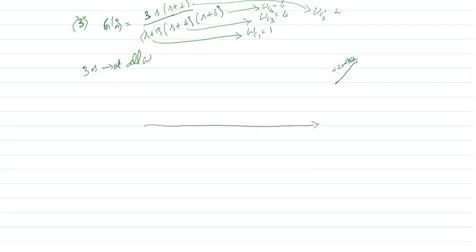Between 0.1 and 1, it is plus 20 dB per decade. Okay, after 1, s plus 2 will function after omega equal to 2, s plus 1 after 1, s plus 4 after 4, s plus 6 after omega 6. So after s plus 1 this will function. Already 3s is plus 20 dB, this is minus 20 dB. So the resultant is plus 20 minus 20, it is 0.